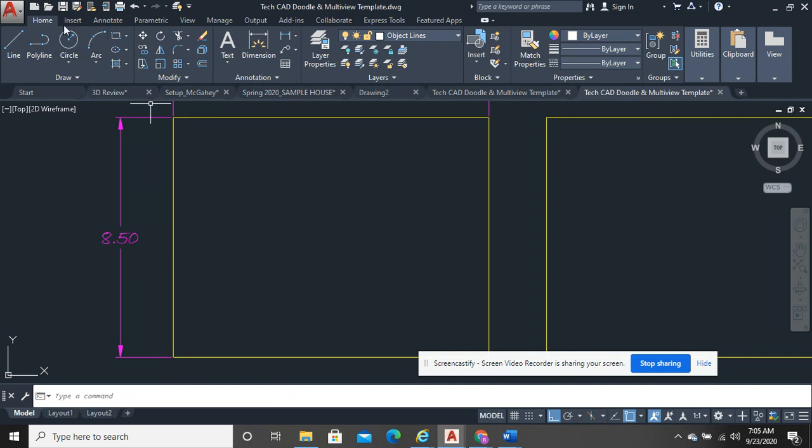But if I needed to do something really quick and just draw something that was completely right angles, like if I had to go over 3, down 1, over 2, down 2, over 5. Another thing you can do, if you're ever doing a closed shape like this, you can hit letter C and the space bar, and it will automatically close it for you.